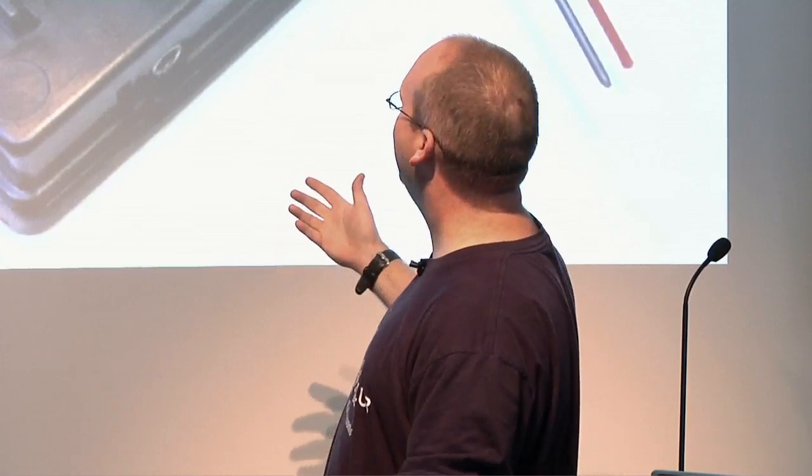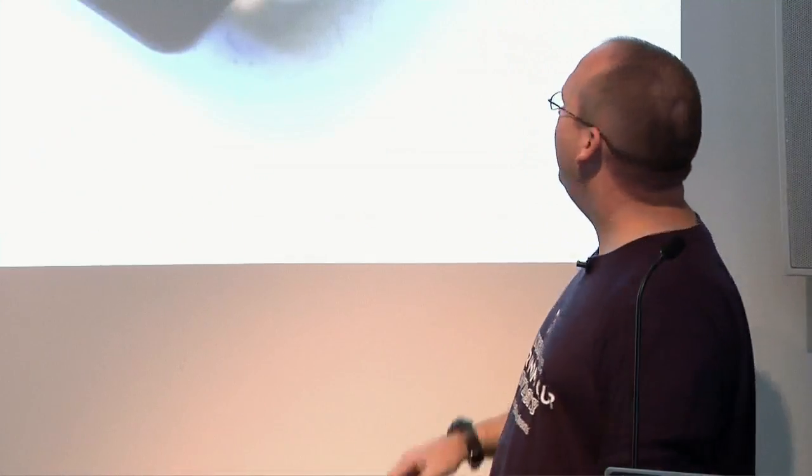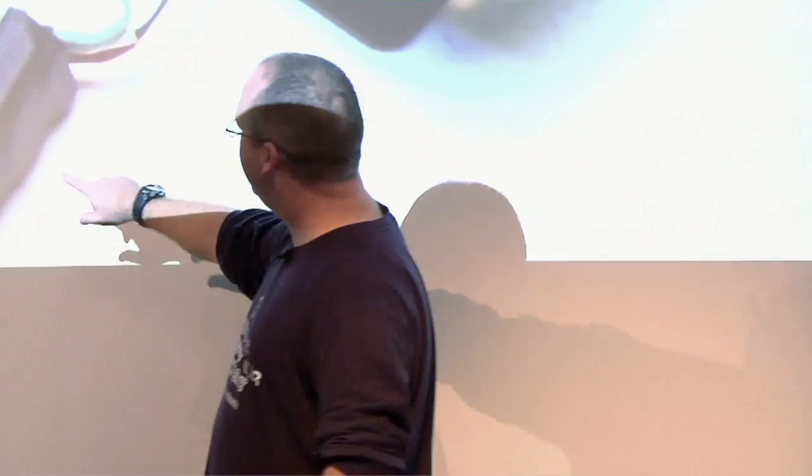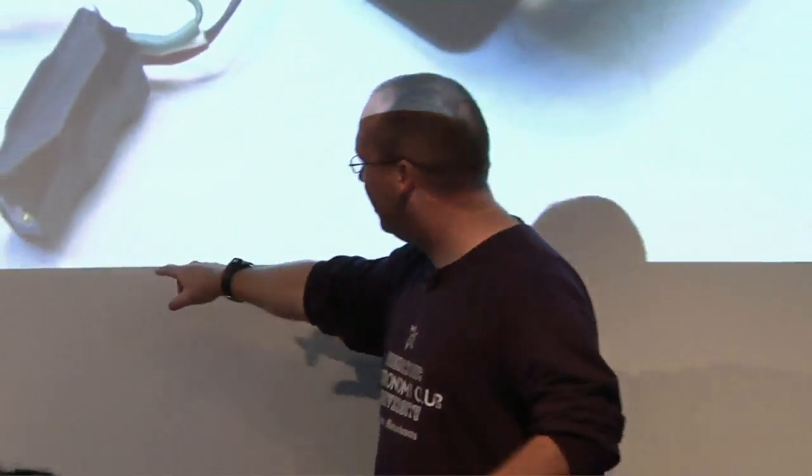So it was like, okay, let's find something that'll hold AA batteries. Luckily, I think Adafruit was where we got this space certified battery holder. We basically sourced a battery holder. We had already done some other projects with this little guy, which is basically a DC to DC switching regulator. And the important part is it's got this little adjustment knob on the front of it. And we figured, all right, we'll feed it with AA batteries, and then we'll let this little switching regulator fake the phone, or trick the phone, into thinking it's got a lithium battery.